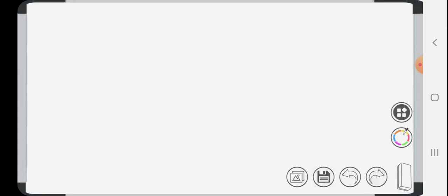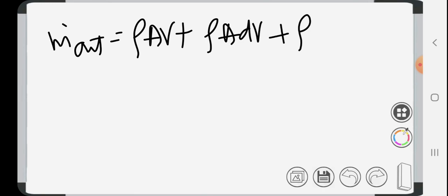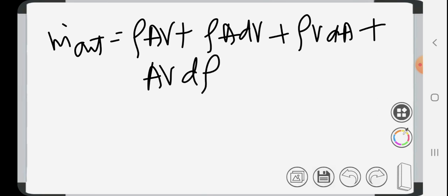So m dot out will be rho A v plus rho A dv plus rho v dA plus A v d rho.